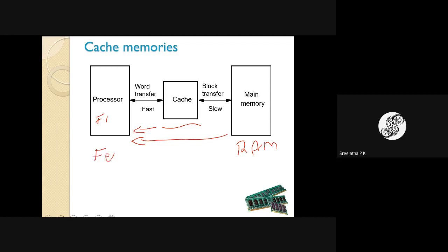Fetch the data to the processor, decode the instruction, means the processor understands what that instruction must do, and then execute and store the results. Okay, those are the steps in the execution of an instruction. So the processor sends the fetch instruction step first.